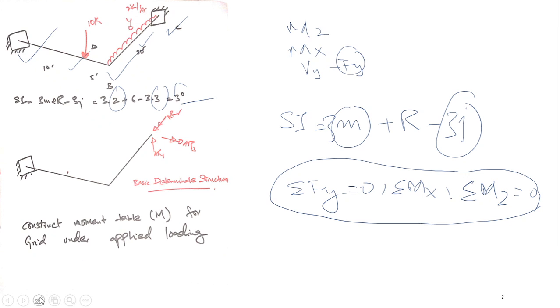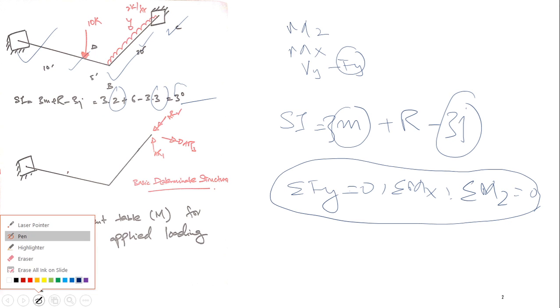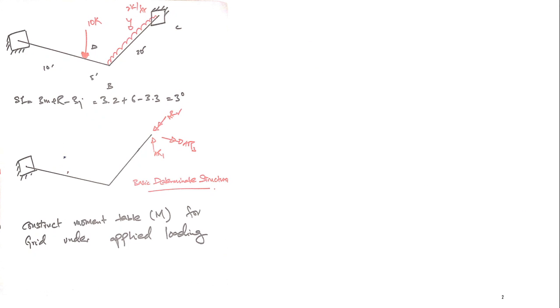Actually, you should know that in this grid the loading is there. The fixed support shall develop this reaction and this moment. Also a moment here would be developed. So, 3 reactions: the moment in the x direction, the moment in the z direction, and the vertical reaction. So in grids, there are 3 reactions at a fixed support.